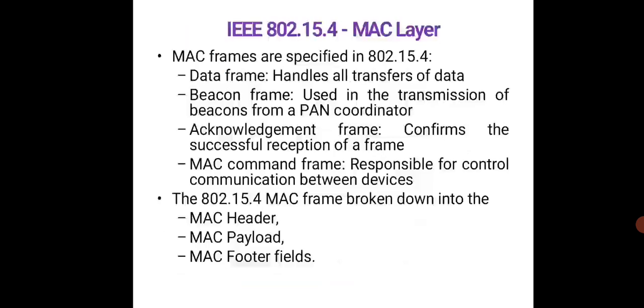So here MAC frames are specified, which is the data frame, which handles all transfers of data. Then the beacon frame, which is the transmission of beacons from a PAN coordinator. The acknowledgement frame, which will confirm the successful reception of a frame. And you will also have a command frame, which will be responsible for all the control communication between devices.